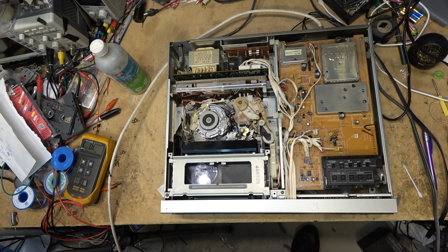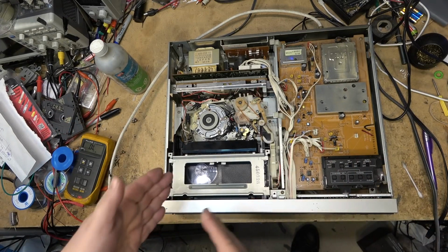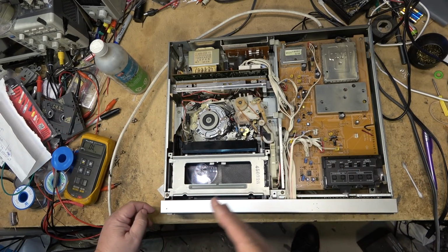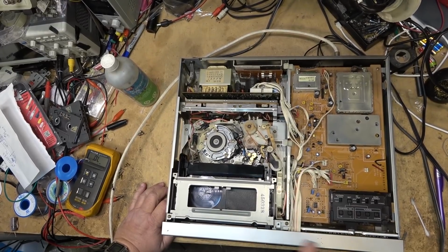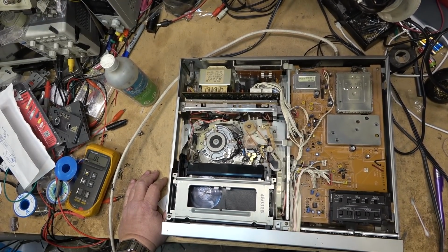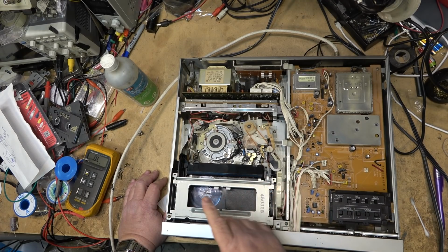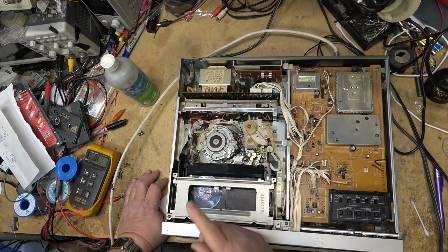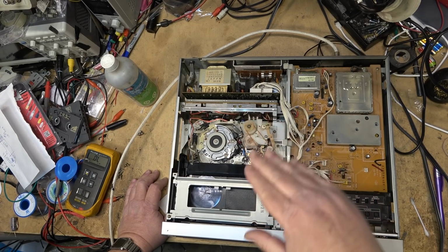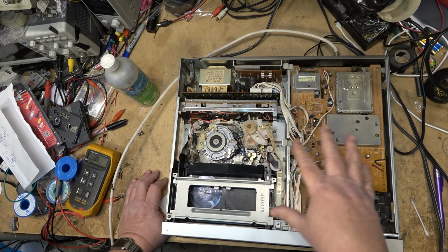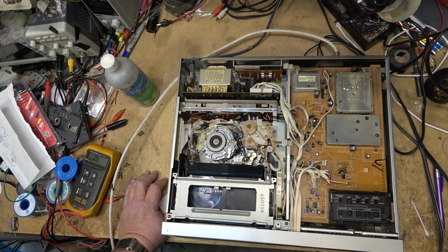But in this case, resistance had built up on it, and because it's using a resistive ladder to measure the voltage drop, to determine what mode it's going to go in, get a bit of oxidation on the contacts, and now we don't have a good read for the proper resistor that's placed in line with the control line that's being read for voltage. Because essentially what they're doing is it's just multiple resistors grounding out multiple resistors, and it's causing a voltage drop, and it's measuring that voltage drop, and that's what's determining what mode it's going to go in.